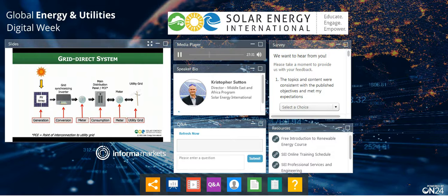And that's why at this point, we see that we have these arrows on the right side of distribution that go both directions, because we can export to the grid or bring power in from the grid based on how many kilowatts we're producing versus consuming. So that part of the system, we can send energy both directions. Now, in order to send energy both directions through that utility meter, that utility needs to replace that with what we think of as a bidirectional.